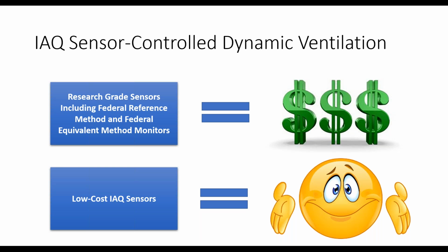So an example of that might be if I've got a sensor that is not particularly good at predicting an accurate pollutant count. So maybe it's off by a factor of 100 or something like that. But it does tend to show change in pollutants fairly well. So in other words, we do see a percent change, even though the actual concentration count isn't accurate. A ventilation manufacturer might want to know, okay, this sensor will work for me as long as I can set my controls to respond to changes in pollutants rather than absolute concentration levels. So that's a question we want to know about these sensors, how they work and how well they work. But again, there's no set way to test them.